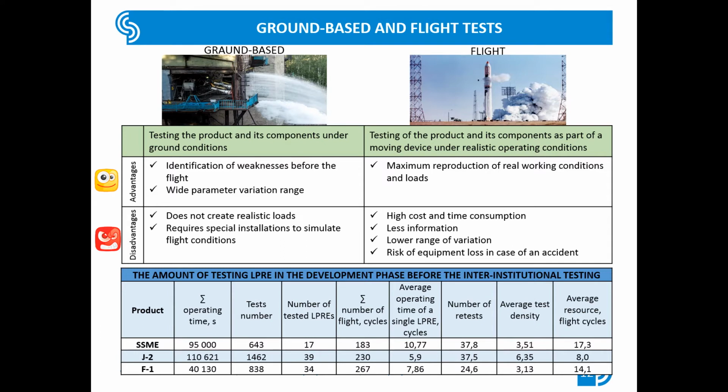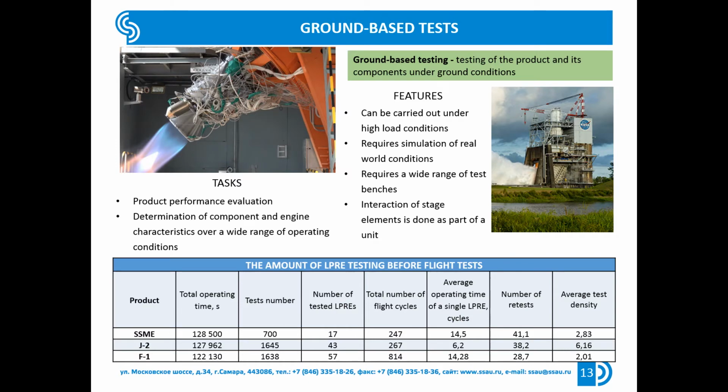However, with all the advantages of flight tests, they have the following disadvantages. Flight tests are very expensive, and their cost will increase dramatically due to launch failures when not sufficiently reliable LPREs are tested. Flight tests have less information than ground tests because of the limited number of measurement instruments and telemetry channels. Flight tests may allow for significantly less variation in factors affecting the physical process of the LPRE during testing. In normal bench tests, it's not possible to create performance-like conditions in all cases.